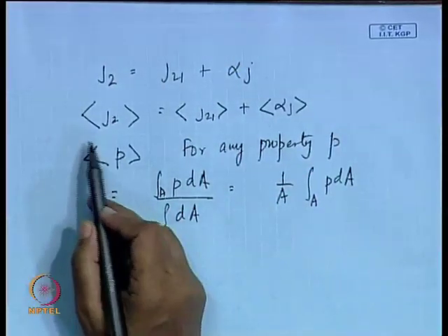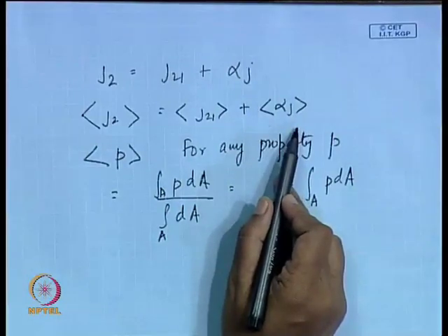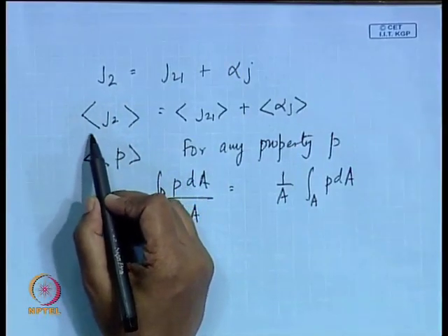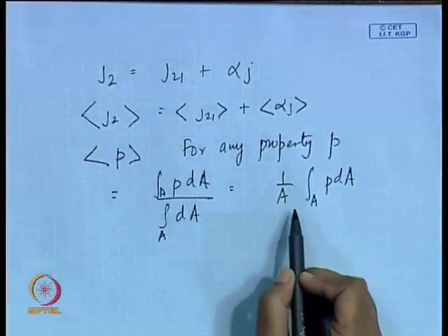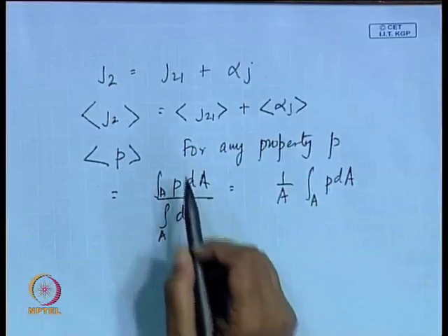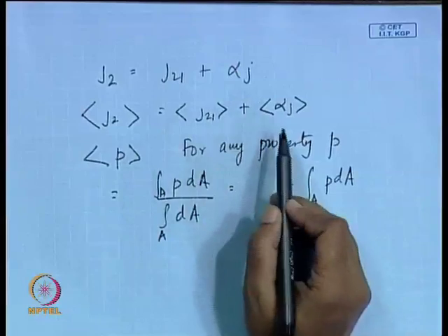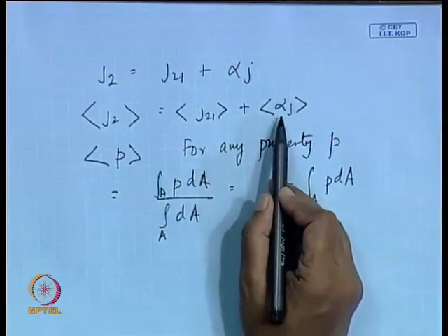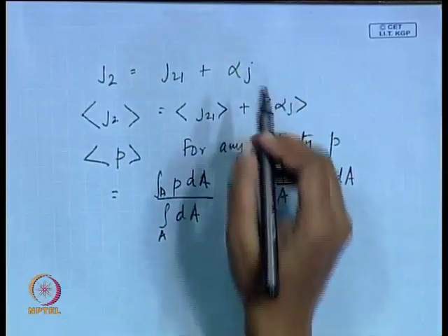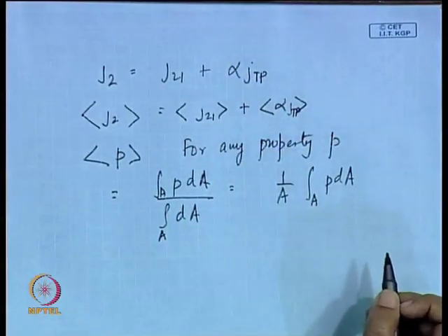So, when I put these brackets across the individual terms of these expressions, this is the average volumetric flux of component 2 averaged over the entire cross section, which is nothing but the integral of J2 dA by A. This is the average drift flux averaged over the entire cross section, and this is the product of volumetric concentration and volumetric flux averaged over the entire cross section. I would just like to make a correction: they are all referred to the two phase values.